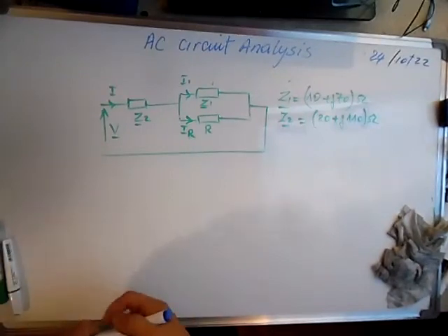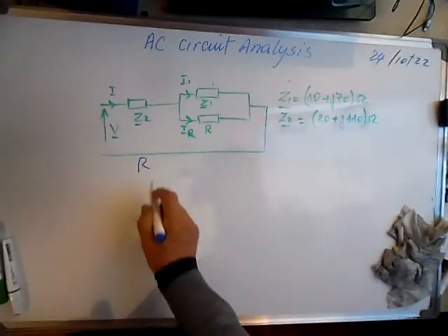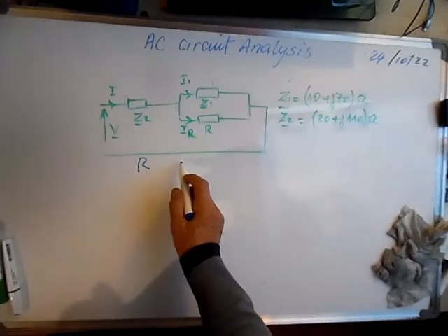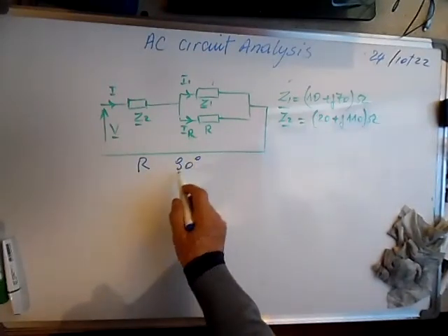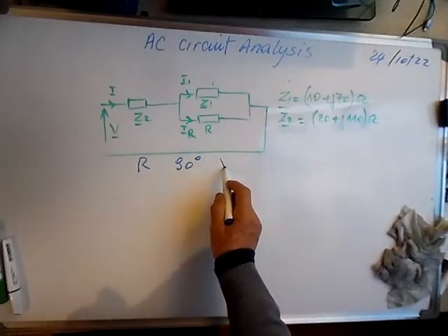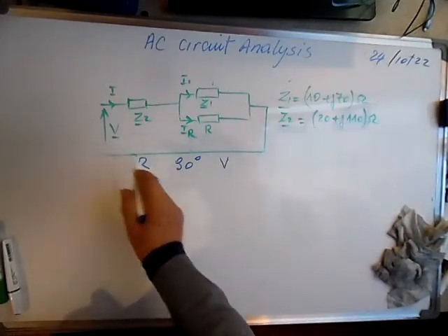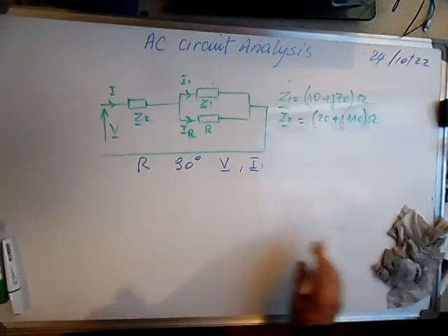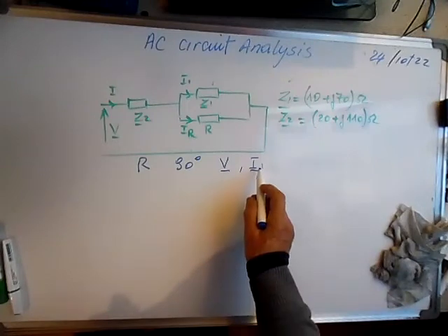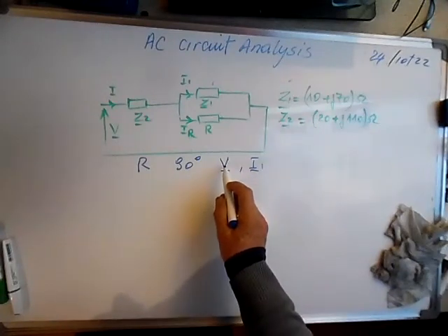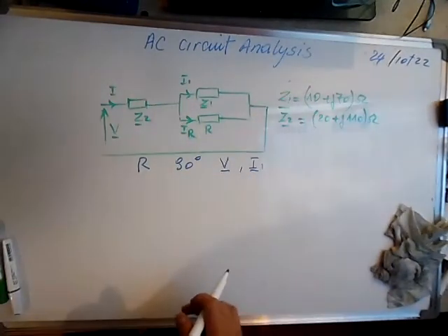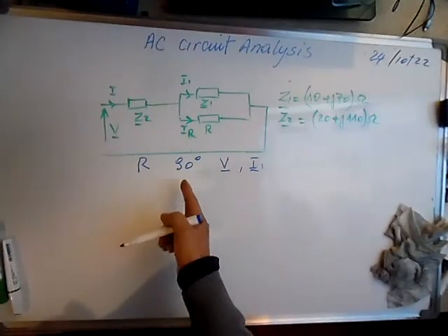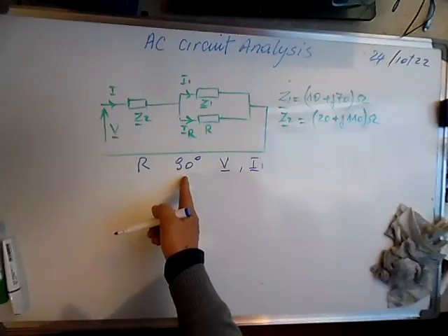We have a circuit like this. Following the circuit, we are asked to calculate R that will give us a phase lag of 90 degrees between the source voltage and the current I1. So we have to write this current as a function of this, and then try to calculate the resistance R.